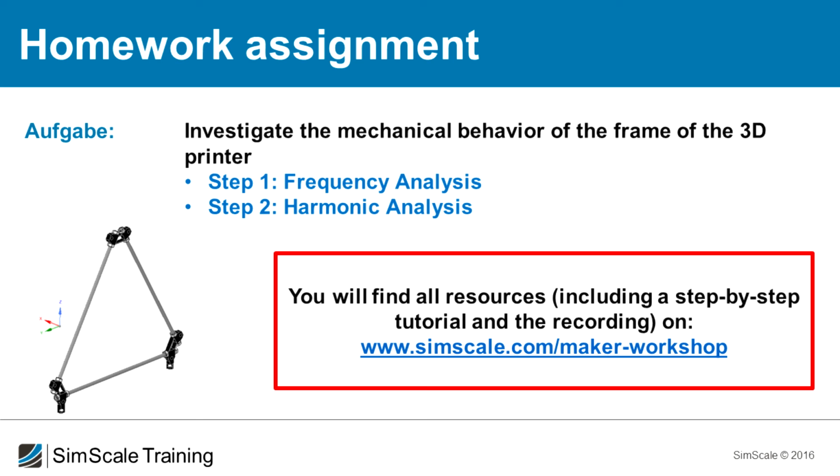And then you are asked, on this next level, to create a harmonic analysis based on these results. You can reuse the mesh for this, so you don't have to create a new mesh, and you just have to adapt some small things. And we will also provide a step-by-step instruction for this.